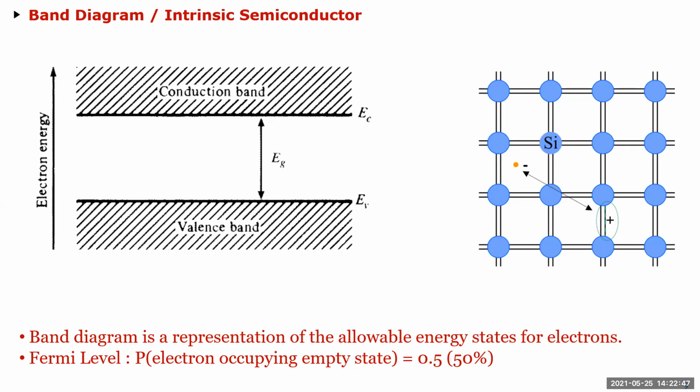There are a lot of devices which have been created just by people playing around with band gaps. A lot of your power amplifiers actually have a device called a HEMT, and those devices were purely fabricated out of people playing around with band gaps, I mean band diagrams. So I think band diagrams, at least for knowing the overview, are a good idea. If you look at this band diagram here, the x-axis is the length of the device, or whatever you want to call it.